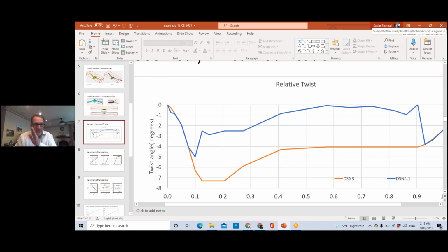Without using rudder or anything, I suddenly get a big side slip, and that will expose whether or not there's a vulnerability to a spin departure or a wing drop or anything from that kind of asymmetry. So it's a nice consistent way to explore it, and it looks very much like what pilots might do or the airplane may want to do: landing approaches, banking and turning, and yes, it's pulling higher CL, so you're getting closer to stall, and it's a great way to expose issues.